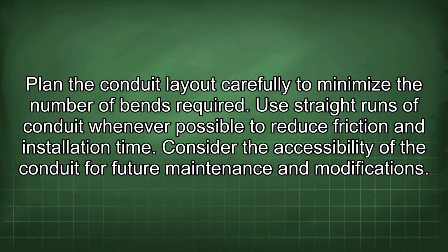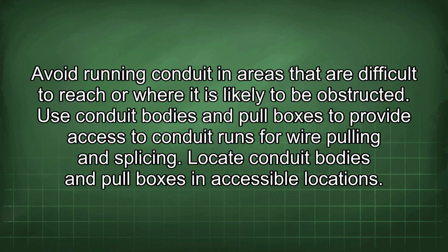Plan the conduit layout carefully to minimize the number of bends required. Use straight runs of conduit whenever possible to reduce friction and installation time. Consider the accessibility of the conduit for future maintenance and modifications. Avoid running conduit in areas that are difficult to reach or where it is likely to be obstructed.